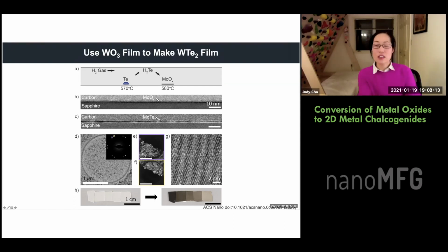Oh yeah, that's a great question. Anybody who does transport measurements of nanoscale materials spends the most time on what kind of contact you have, right? Right now, we etch away the contact area before we deposit metals, and then we do some etching tests to make sure we've gotten rid of a lot of oxide.